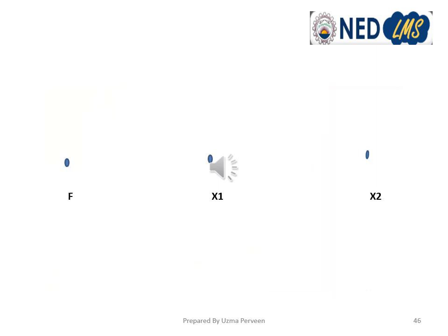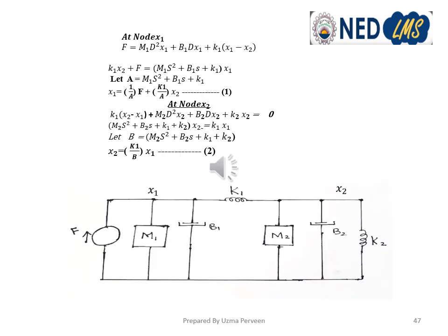So here is how we mark the variables as nodes to construct the signal flow graph. These are F, x1 and x2. As we have three variables F, x1 and x2, there are two possible output nodes, x1 and x2. It means that we'll need two equations, one for x1 and another one for x2.